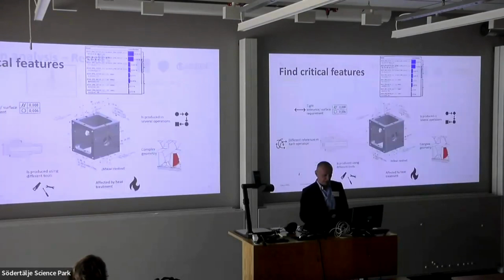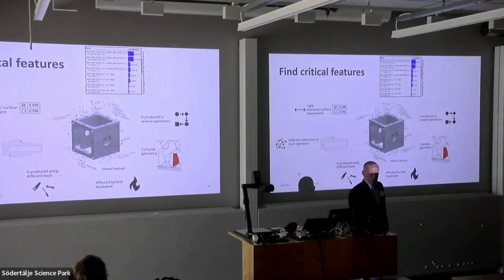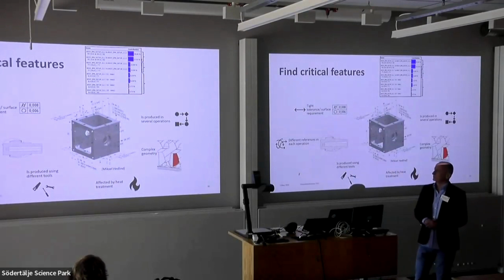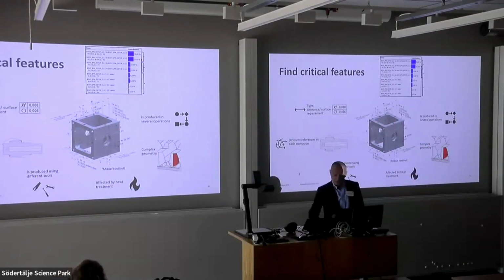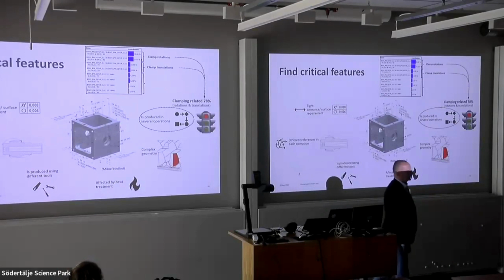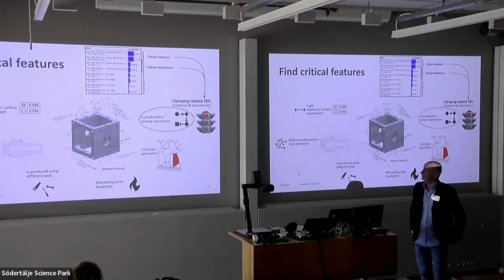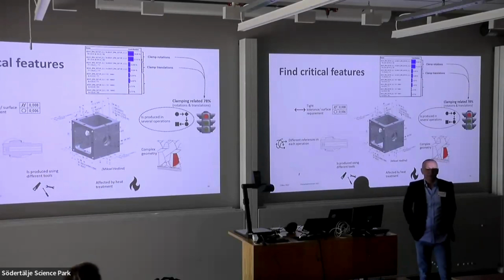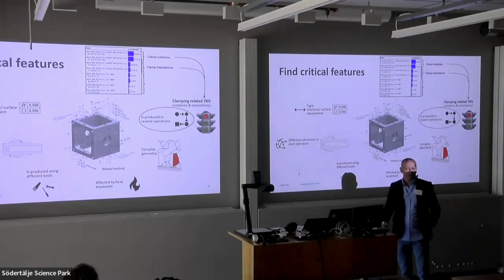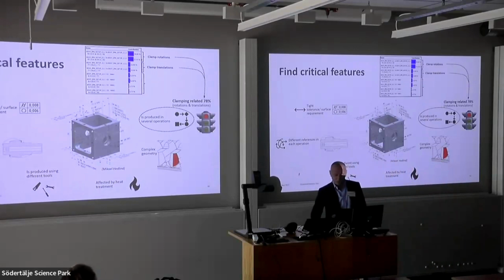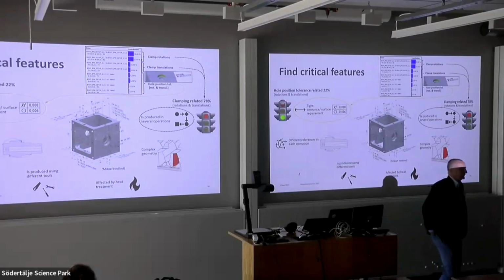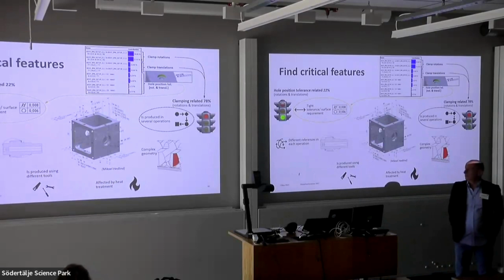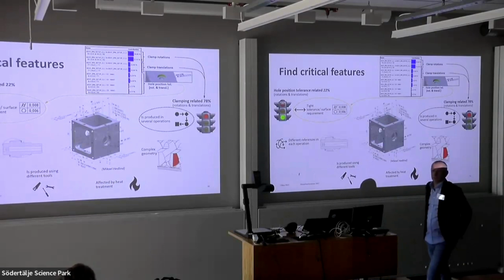Finally, to summarize, by having the contributors from both part level and assembly level variation, we could assess the clamping process quality. And as you see, 78% of variation is coming from clamping. So maybe we need some rework and rethinking, changing in the process or tightening tolerances or lowering the variation. And then hardware quality was good enough. We got a green light. And that's what was our contribution to the project.